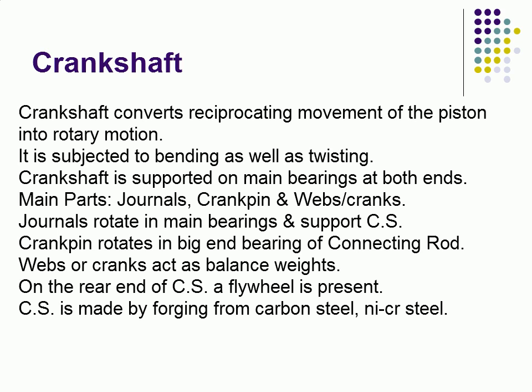The next important component of engine is the crankshaft. Crankshaft converts reciprocating movement of piston into rotary motion. It is subjected to bending as well as twisting. Crankshaft is supported on main bearings at both ends.